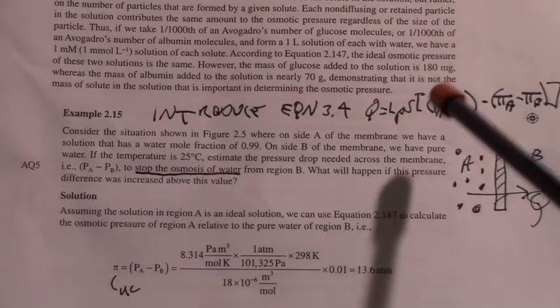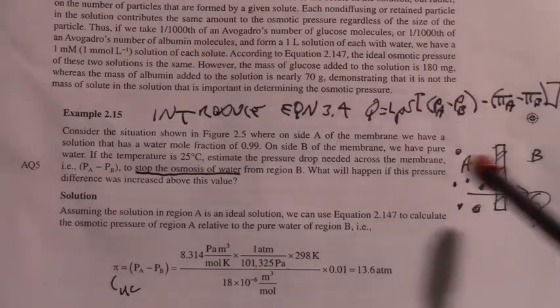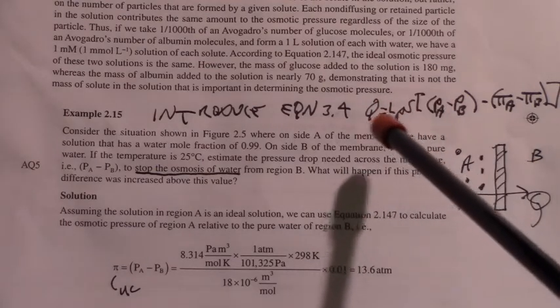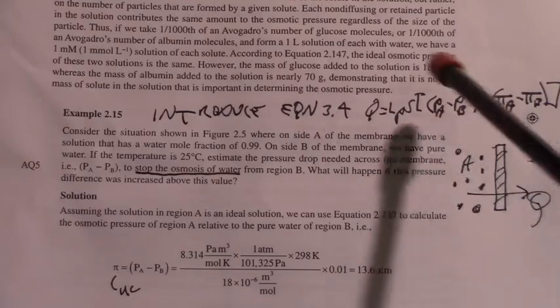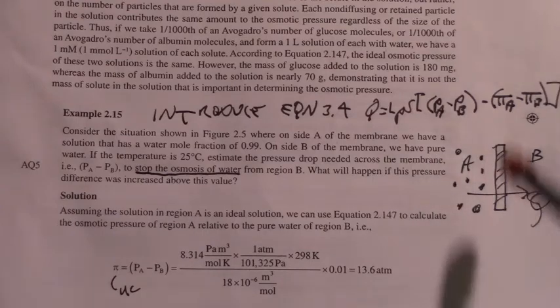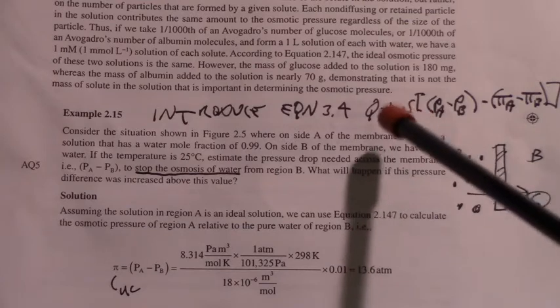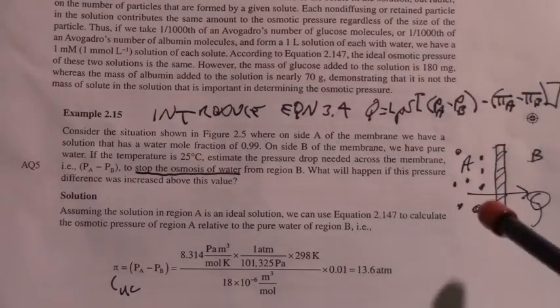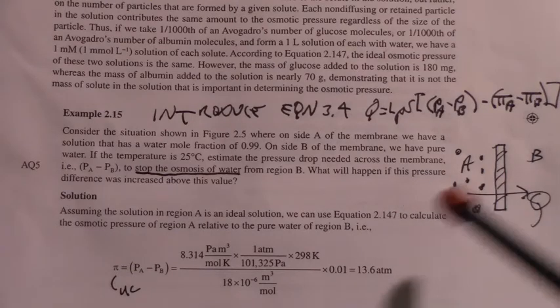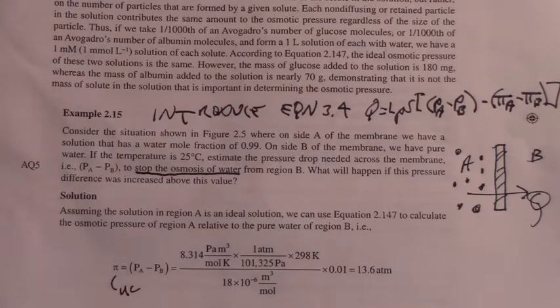Then you would know by intuition that as you increase the surface area of the membrane, the cross-sectional surface area of the membrane perpendicular to the flow, you should get a higher volumetric flow rate. So that's why they separate out in this conductance term the actual surface area of the membrane, because as the engineer, that's one of your degrees of freedom in terms of whatever it is you're designing. And L sub P is called the hydraulic conductance, and hydraulic conductance is independent of the surface area of the membrane, but depends on the nature of the fluid itself and the internal porous properties of the membrane.